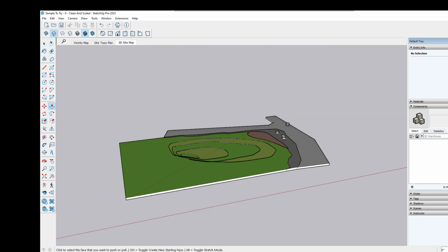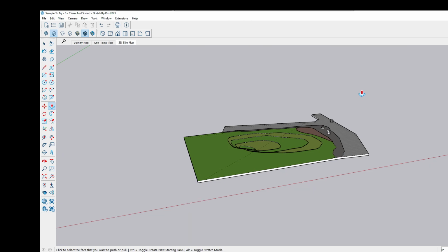It's huge, right? And so when we put it into our landmass slicing one, it's a little bit easier if it's a little bit smaller. So I'm going to press the scale button. Scale. First, let me highlight all that stuff. Scale. Pick this bottom corner over here, and it goes to the opposite corner. Come over and type 0.1.